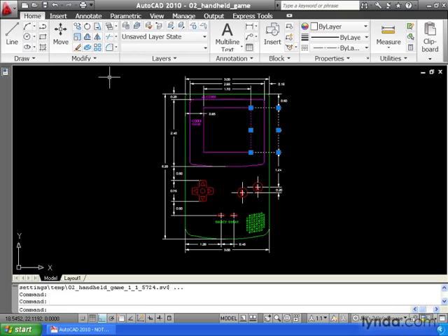I'm going to move up into the ribbon and I'm going to left click on this tool. This guy happens to represent erase. Notice that I launched the tool and that line work is now gone. So a left click allows us to make a selection, whether it be entities on our screen, an icon in the ribbon, or an option in one of the menus.